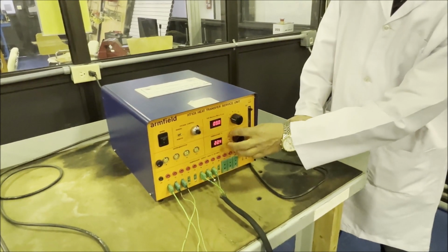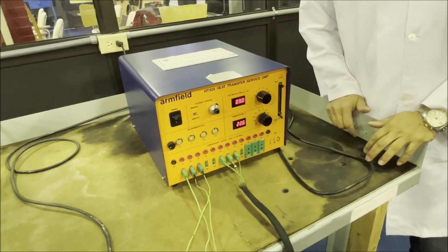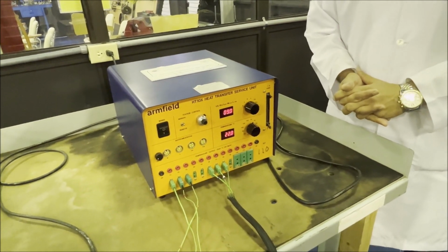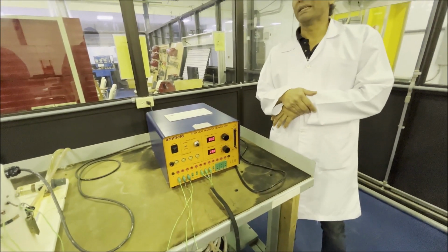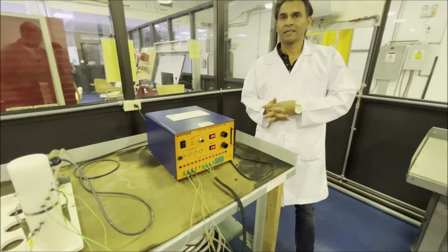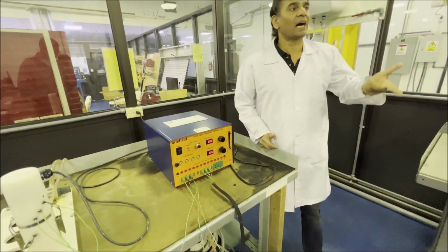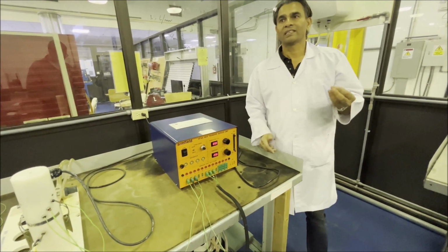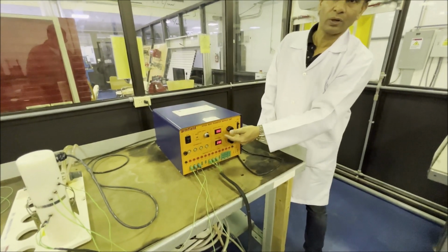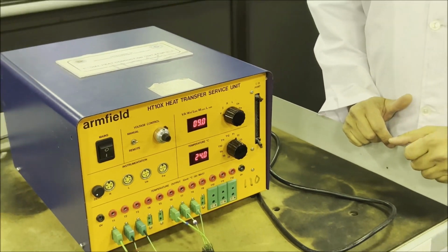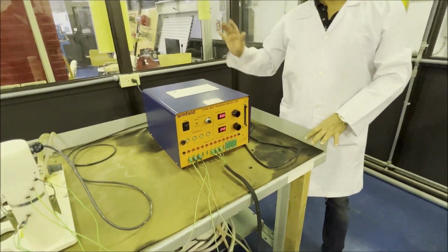Now for the temperatures T1, T2, T3, 6, 7, 8: 4, 5 is not there, so no need. Instead of 4, 5, we have to calculate from 6, 7, 8. After 20 minutes, once steady state is reached, when there is no change in temperature with respect to time, we will take the reading. So we will wait at least 20 minutes. Next we will make the voltage 12 volt and repeat. And at last, make the voltage 0 and close the water.